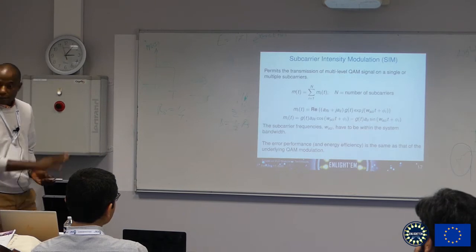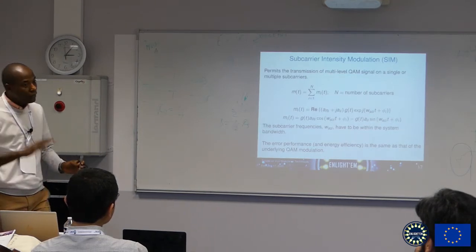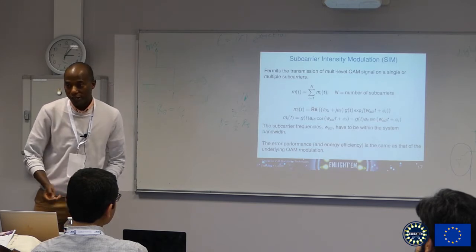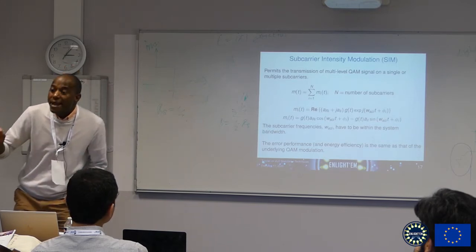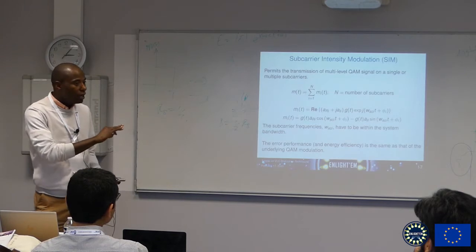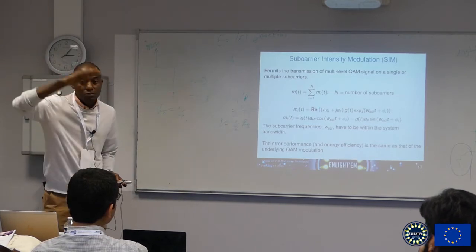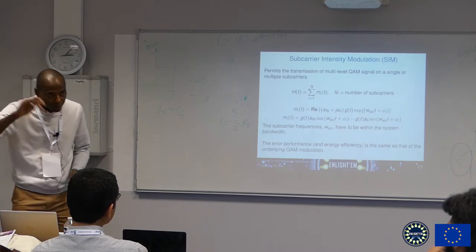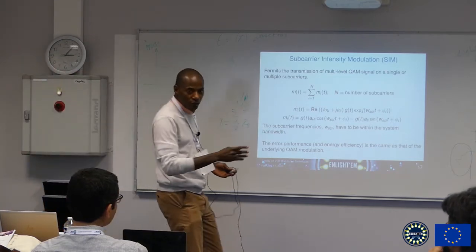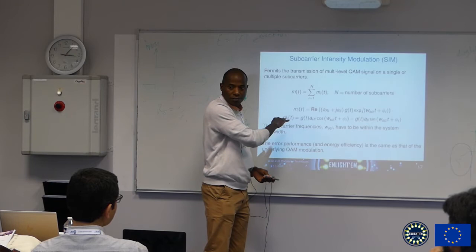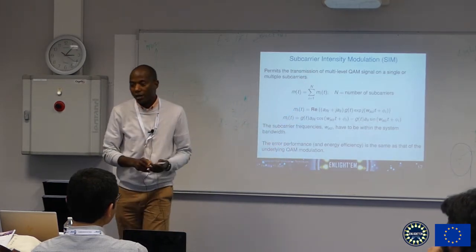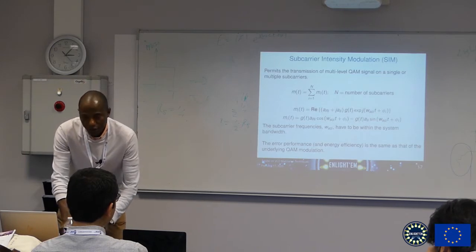Easy. So that is pulse-based. Those are very good, particularly if you're looking at things like sensor networks, low energy systems. The data rates might not be the best, but they are very good. They are robust as well because they're just based on pulse level, energy levels. We look at energy, done. Non-linearity is not so much of an issue when it comes to pulse-based. But when it comes to continuous time, then we have to be very careful about non-linearity.